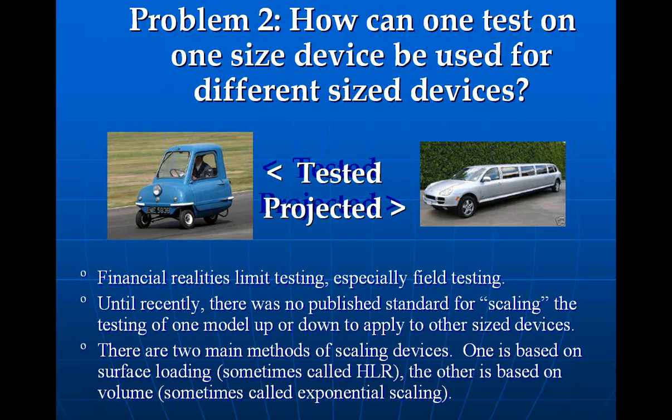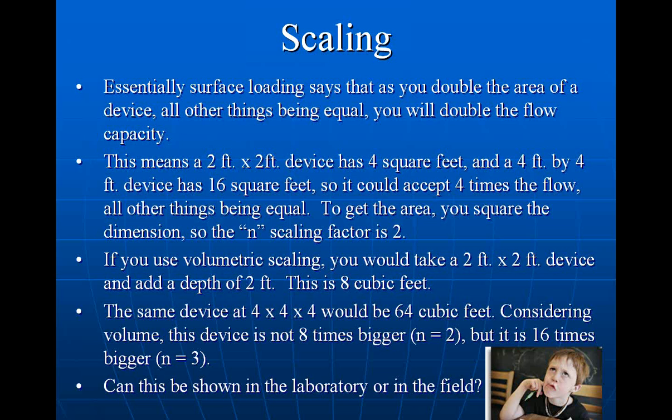And there are other people who base scaling on volume, which is sometimes called exponential scaling. Suffer me just a minute of math here, please, because people don't understand where these N factors in scaling come from. Some people say, I use an exponential scaling factor of 2.5 or 3.